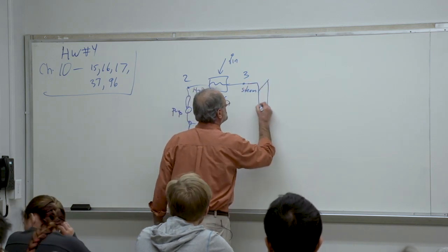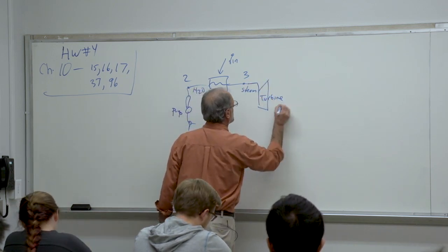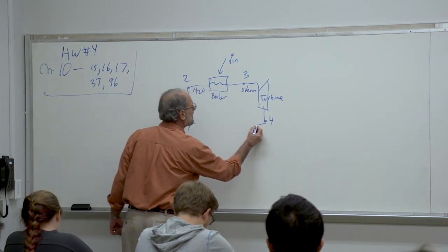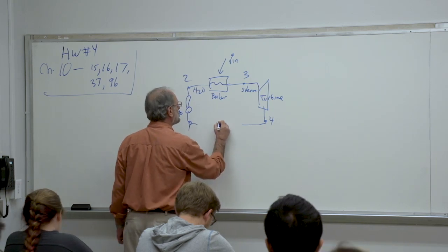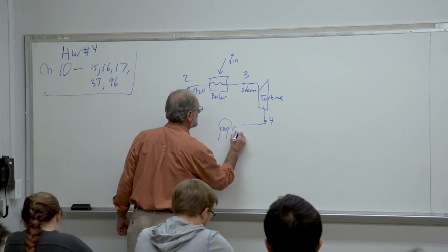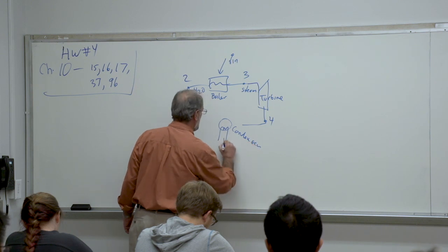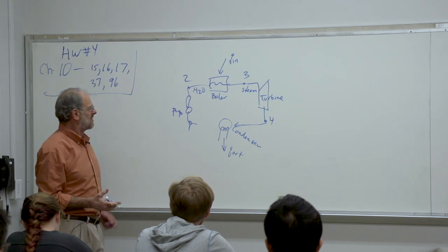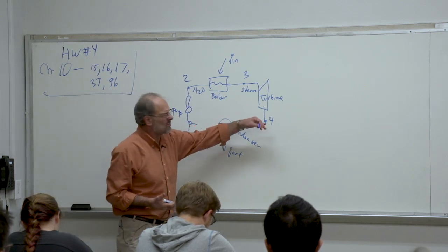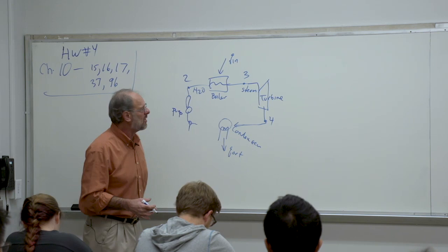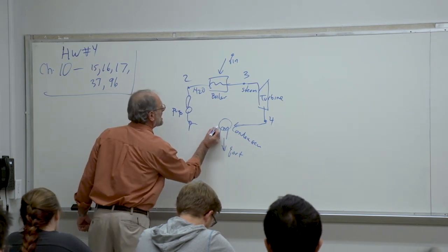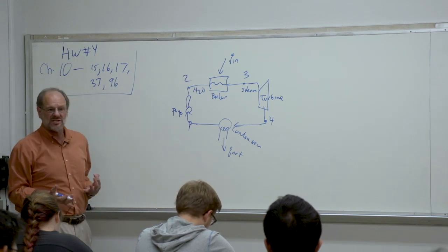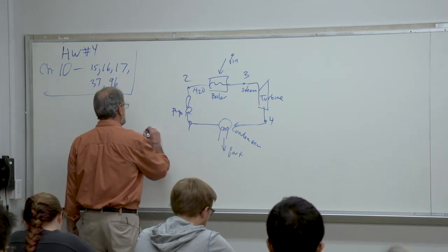This steam now goes through a turbine where work is done, and as we expand through the turbine, the pressure drops, and then we go into a heat exchanger, which we call a condenser, and here the heat is removed. Whatever steam we had coming out of the turbine, again, could be saturated, could be high quality two-phase, but nonetheless, we're going to condense the vapor back into a liquid, and we go right back into the pump again. So this is our basic Rankine cycle.